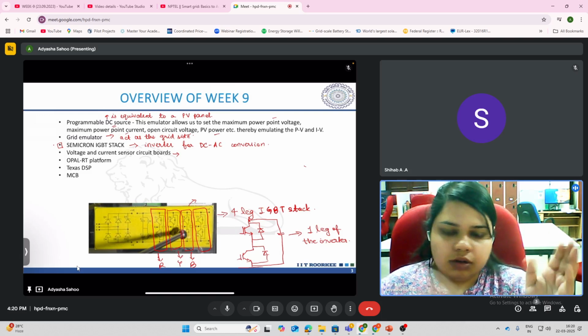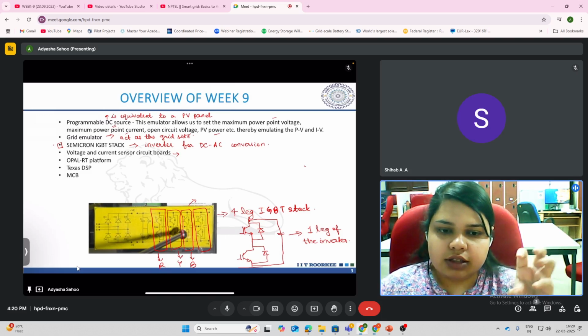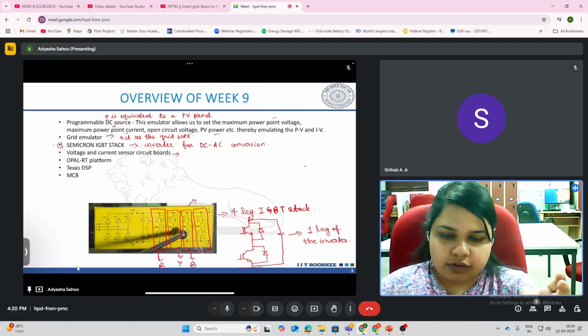So in the islanded mode, all these inverters require some reference signals to work upon the control logic. As long as you have the grid, they can work in the grid feeding mode. But once the grid is cut off and you are in the islanded mode of operation, these inverters do not have any reference signals with them, so they cannot function. So among the available inverters in the system, one of these inverters now acts as the grid forming inverter.